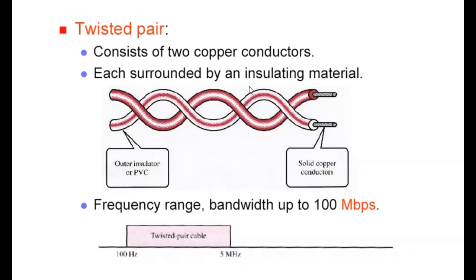It's generated by the magnetic field of other devices. So if a cable goes beside an air conditioning unit, every time the air conditioning unit is switched on, it generates a magnetic field. If that wire is in the vicinity of the magnetic field, it will generate a current inside it. That current will cause noise, and the original signal becomes unrecognizable.